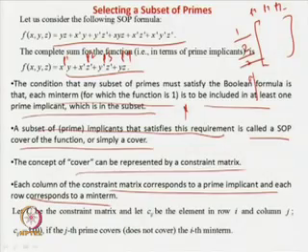So in the next lecture, so next to next lecture, in these 3 lectures we will only see the exponential algorithm, and after that we will go for a heuristic. In this lecture we will see that the problem is difficult to solve at a lower complexity because it is an NP-complete problem. So what is our agenda now? At least we have seen that if you go for the tabular method to generate the prime implicants, you have to blow the function up. But if you go for iterative consensus, at least for generating the primes you are not blowing up your function.